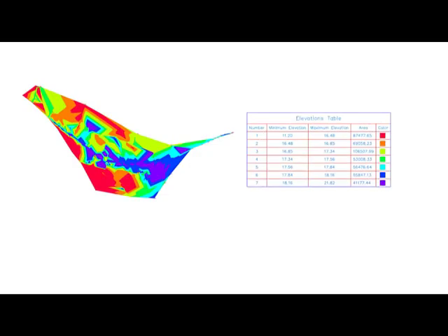There are different softwares that can be used, but one of the softwares to use is Civil 3D. With Civil 3D, you can actually input all these points with the projection coordinate system. And with that, the points will generate in the actual location in the whole world where you have selected as the coordinate system. So it is going to generate it for you automatically.